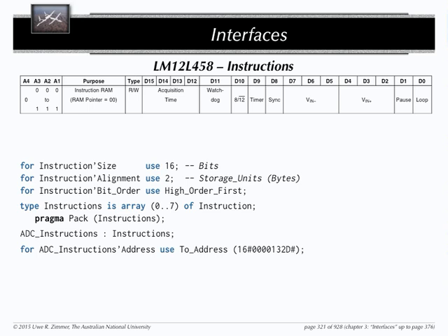If this is a volatile memory address, I have to, as a compiler, always reload this. Every time your high-level program is reading from that one, you cannot assume that the last read is still the same. You always have to reload it from the memory bus. Make sense? Cool.